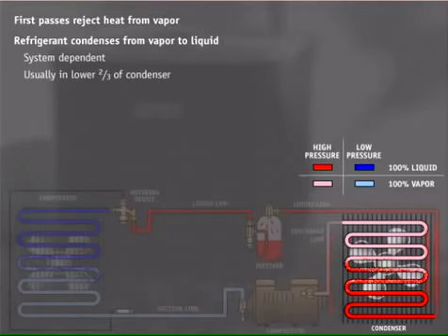Once the refrigerant is 100% liquid, further rejection of heat starts to lower the liquid temperature to the evaporator temperature. This is an important process because it will reduce flash loss in the evaporator, so more of the vaporization of the liquid in the evaporator can be used for useful refrigeration or air conditioning.